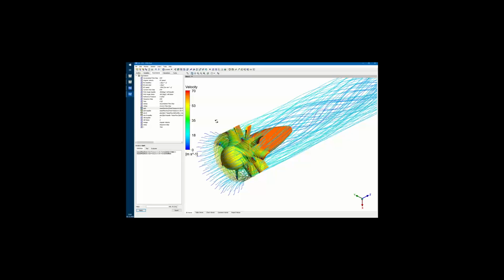Okay, great, thanks. Next question, can you do heat transfer with your model in CFX? And that I can answer. The answer is yes. We can do a conjugate heat transfer simulation in CFX. And we need to add the solids, of course, in this case. Is there something else you would like to add, Sasha?